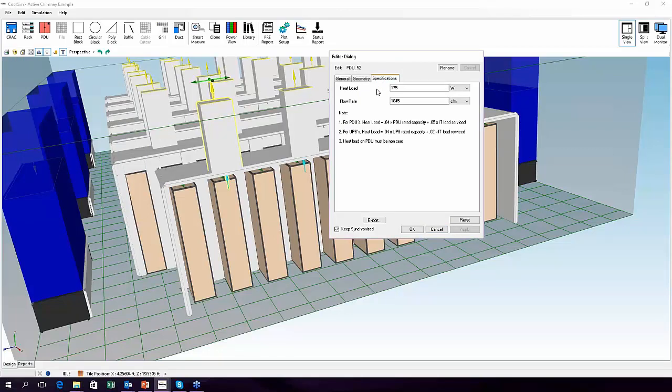Normally in a PDU, if you set it for 1 kW, it's going to produce roughly 156 CFM of air. That's generally what's required to handle a 20-degree delta across those units. But if you're modeling it as a fan, then those numbers aren't quite right. It produces a lot more air for the wattage.